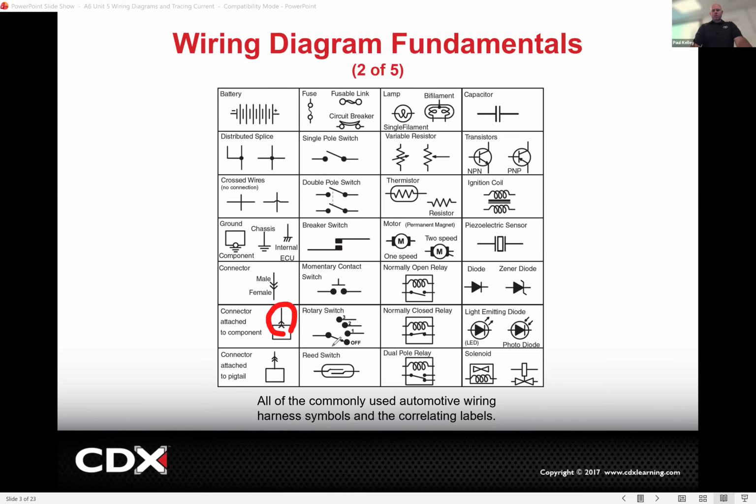And here's another type of switch. This type of switch could seem confusing because if you notice right now we're in off, right? Well, can you think of your blower motor? When you jump in the car, you turn your AC on, or your heat in the unlikely event here. You can turn it to off, right? That's where this is right now. What if you turn it to speed number 1? That's when it's like this. What about speed number 2? That's when it's like this, right?